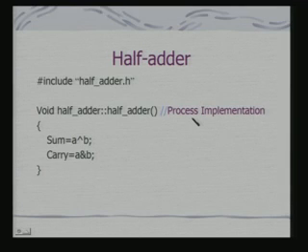Now, if you look into SystemC, as I had started with, the basic concept of SystemC is providing an executable specification language by which you can describe your software as well as your hardware. So, I am referring to this as a system specification language. Please keep in mind that SystemC is not just a hardware description language.